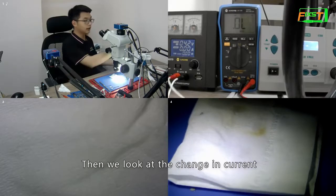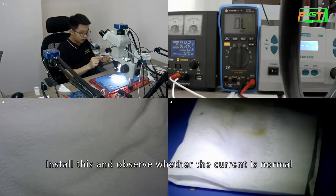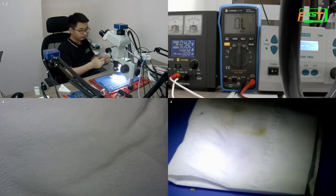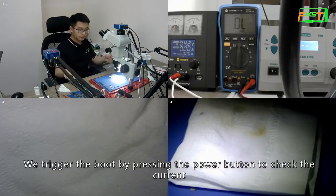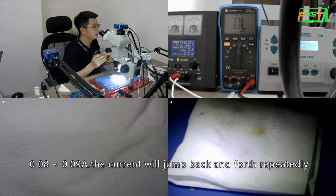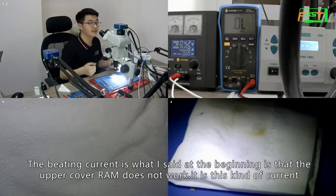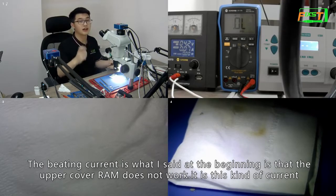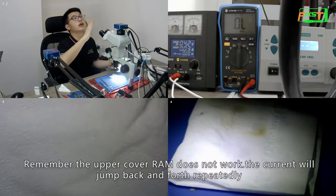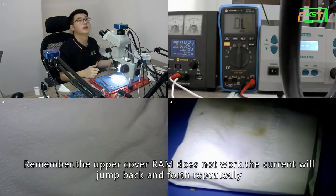Then we look at the change in current. Install this and observe whether the current is normal. We trigger the boot by pressing the power button to check the current. 0.08 to 0.098. The current will jump back and forth repeatedly. Is that what I said at the beginning, that the upper cover RAM does not work? It is this kind of current. Remember, the upper cover RAM does not work. The current will jump back and forth repeatedly.